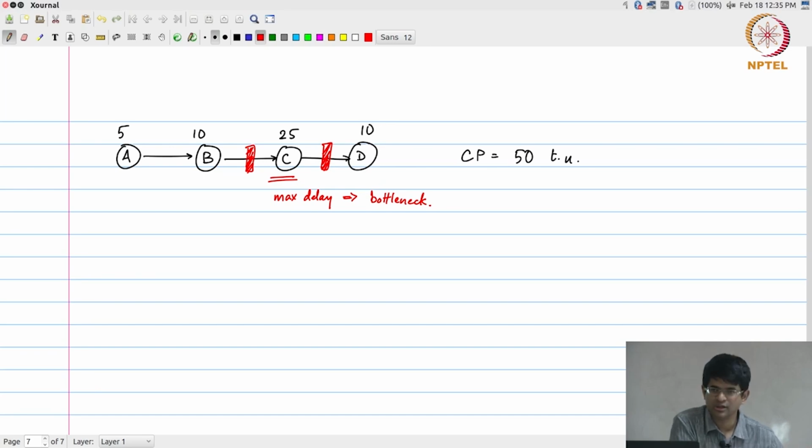Usually this is also called balancing. What you want to do is, if I want to break my circuit into 2 parts or 3 parts, I try and balance things out so that the delays are pretty much equalized on all sides. In this particular instance, supposing I had told you that you are allowed to only use one extra register, what would you do? What is the best that you can do? Where would you place that register?